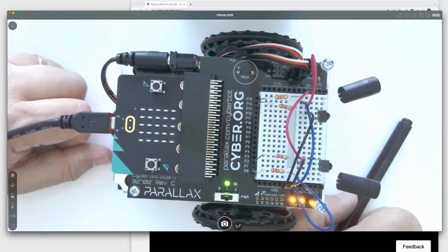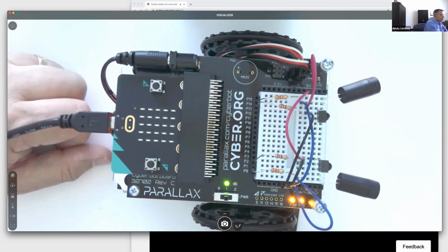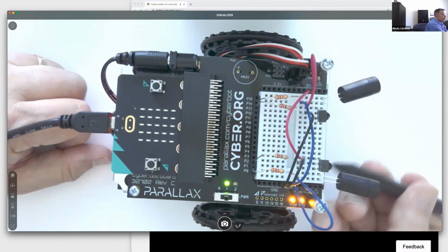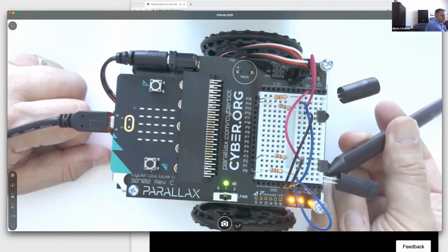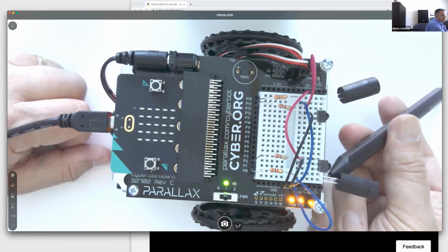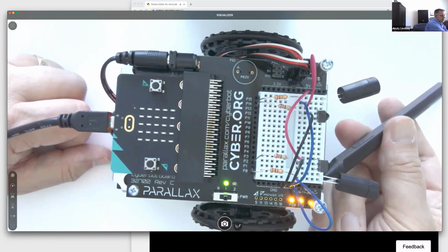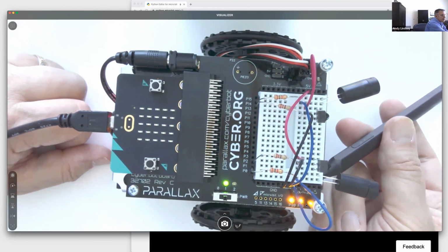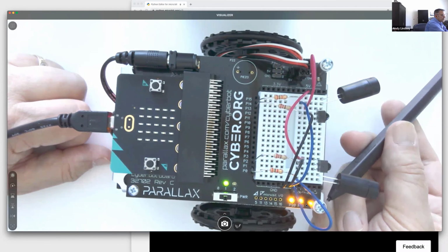Does the orientation of the resistors matter? No, resistors resist the flow of current regardless of their direction. The orientation of the light emitting diodes matters, which is why I made a big to-do about which socket to connect the longer of the two pins, because the diode is actually a one-way current valve. You put it in the correct way, current flows through it and it turns on. If you put it in backwards, it's designed to prevent current from passing through that direction.